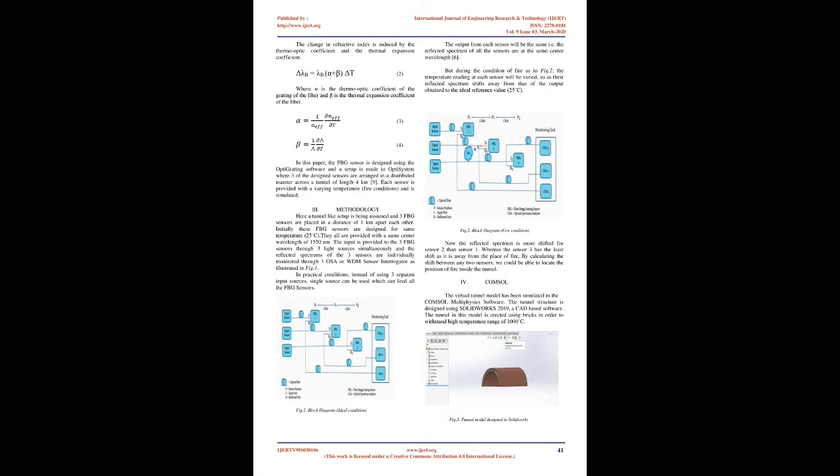If we could locate the position of the fire effectively, we may safeguard the public and properties from a massive accident. The process of sensing and locating is efficiently done by the FBG sensor. The gratings in the FBG sensor cause a narrow range of wavelength to be reflected and the rest of it to transmit through. The center of the reflected wavelength is the Bragg's wavelength. These characteristics of the FBG sensor are utilized to measure temperature or strain changes in structures.